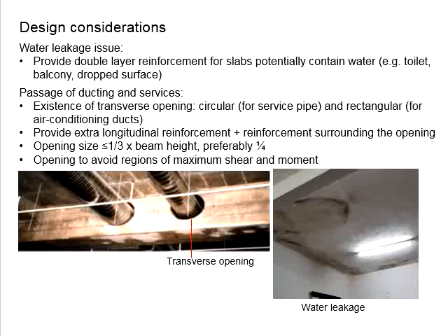Therefore, you will require reinforcement to strengthen the corners of the openings, with the reinforcement aligned on an inclined surface perpendicular to the potential path of cracking to prevent cracks developing at the corners of the openings.